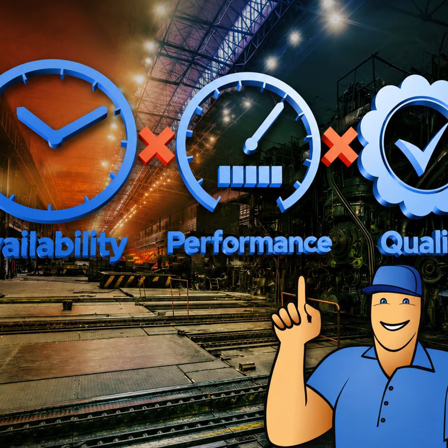Often, manufacturers use one of three options to determine the maximum speed. Some use the nameplate or design speed. Others use a proven maximum, i.e., the fastest documented speed achieved. Still others use the speed they maintain for a full shift without quality issues. That's more realistic, but giving the lowest performance expectations can also risk skewing your calculations. I might suggest one of the first two options, but whatever you choose, be consistent.